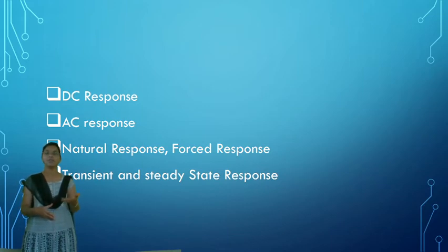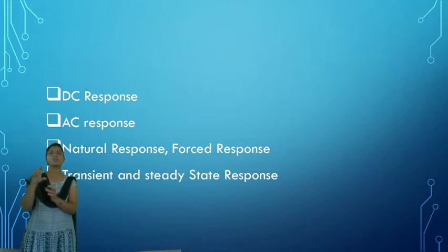If we consider the second order system, that is the underdamped system response. For the step input, what you get is an underdamped response: first it will generate oscillations, and after some time it will stay in a particular band or particular value. Until it stays at a particular value, it is continuously varying, and that is called the transient response. Whenever it maintains a constant output, reaching the input value, at that point the response of the output signal is called the steady state response.